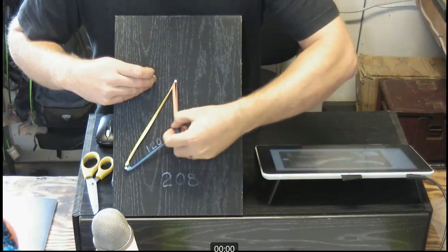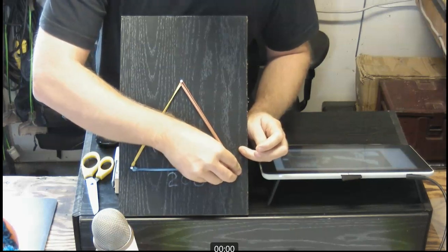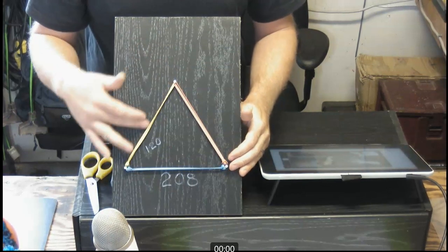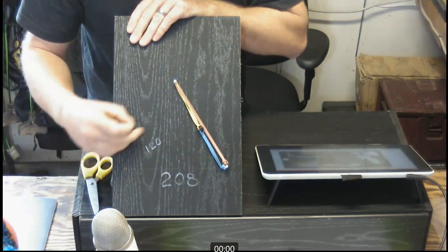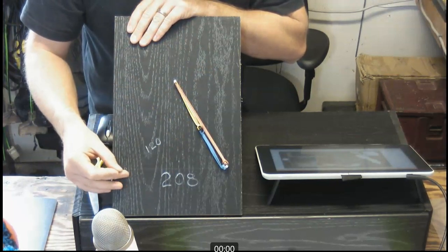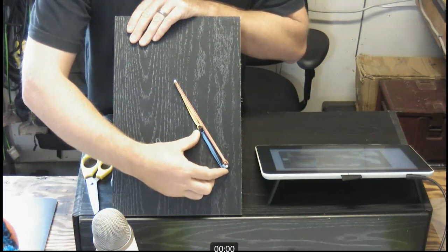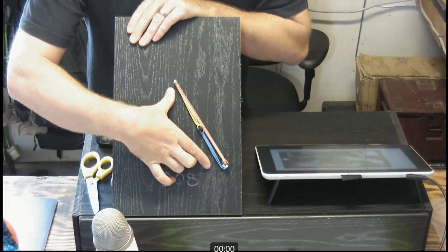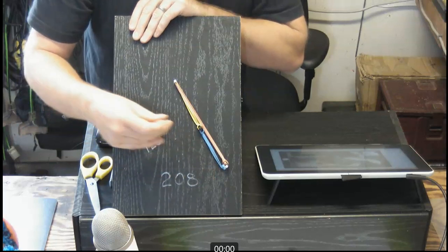Once again, we'll just pull that out over there to the corner. We'll put the nail through the plastic grommet and drop that one in. This is what we normally have. We have a three-phase system that is tensioned across the load. We have voltage across the load, but as soon as we lose any one of our lines, we are going to have one phase that's going to be unaffected, and then the other phases that connect to the affected line are going to single phase across here as well. They're going to be shortened up, and so they're going to see half of my line-to-line voltage. If this is 208, they're going to be seeing 104. If this was 600, these two would each be seeing 300 that would be placed across them.